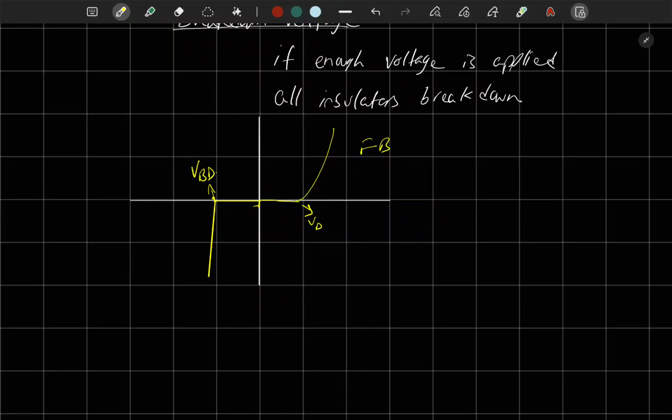And what happens after breakdown voltage? After the breakdown voltage is crossed in the reverse bias, and of course this is a reverse bias, before the breakdown voltage, there is almost zero reverse current, but after breakdown voltage, it becomes another short circuit. So reverse current increases rapidly, and this is called avalanche current, because like an avalanche, the current just goes through very fast.